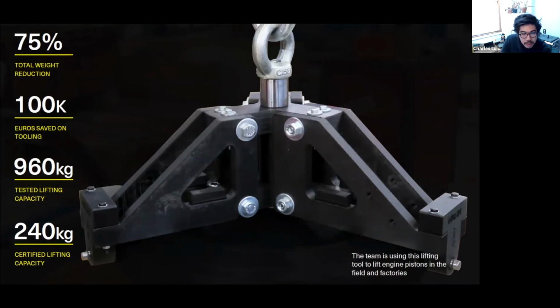Lifespan of hardened nozzles versus brass. So versus stainless, this I don't actually have a great number. There are a number of YouTube personalities actually, I think Modbot, CNC Kitchen. They do some reviews on hobbyist machines. Like we obviously have our own proprietary equipment, but yeah, we use a hardened steel nozzle, and I would say that the lifetime is just like carbon fiber. Continuous fiber is an order of magnitude stronger. The hardened nozzle is an order of magnitude more wear resistant than a brass nozzle.